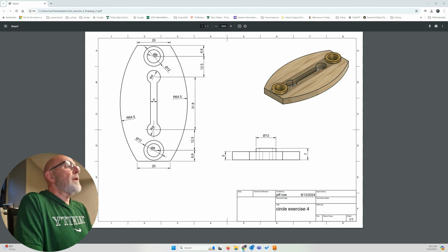And then I'll draw my second group of circles here, and they're concentric, and I'll position them 6.6 millimeters from the top line. I'll draw a construction line connecting the center points of these two circles. I'll offset that construction line by 2 millimeters, both directions.